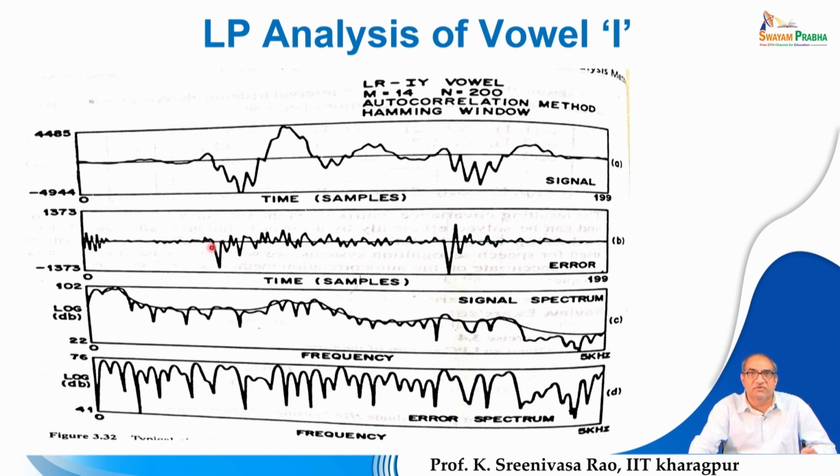That is because this is an impulse. You know that the nature of an impulse is a short span. You can see that the signal fluctuates a lot. In a short span, the signal amplitude changes a lot suddenly. So, this is not predictable. That means by looking at the previous samples, you cannot predict this sudden change. That is the reason you can observe the error at this portion.